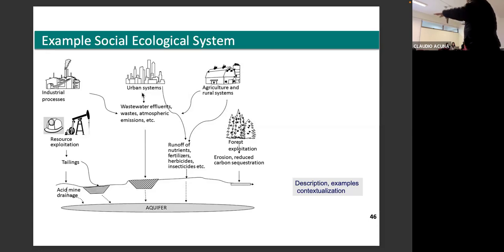So first, you use evaporation. We're losing water. I'm talking about a lot. If you look on Google, you see the ponds are big. It's a big one, 500,000 square meters, one pond. They are evaporating about 500 liters per second. We measured the square meters with Google. Okay. This evaporation concentrates the brine from 0.6 to 6%.